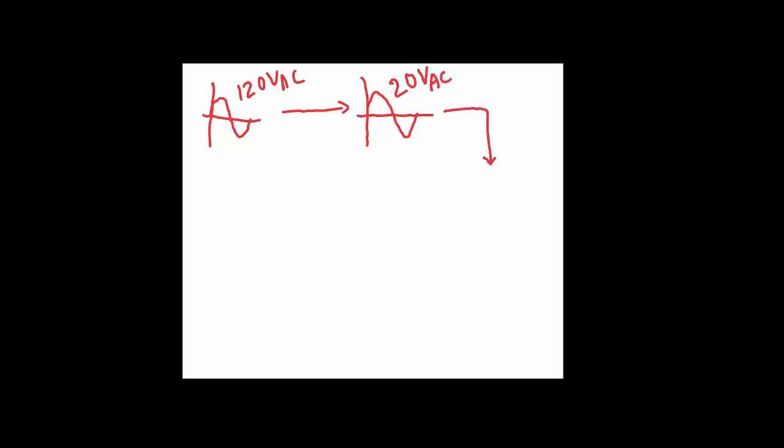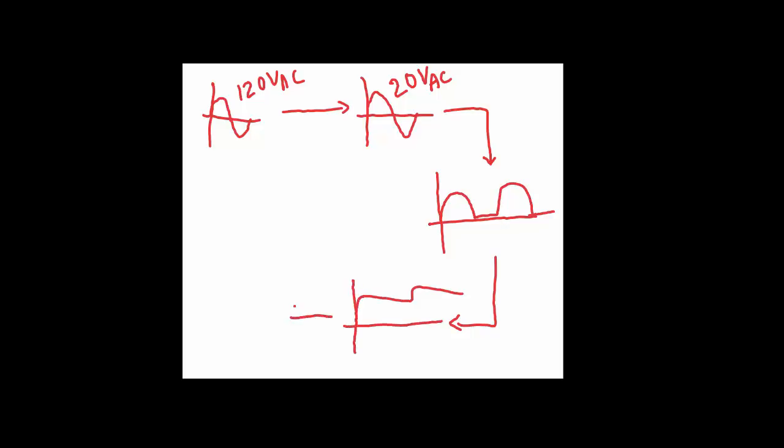So that's what a DC power supply consists of, which is going to be a wall outlet, a 120 volts AC signal, which is passed through a transformer, which is going to step down the signal. Let's say, for example, in this case, I'm going to consider it as 20 volts AC. And then this signal is going to pass through a rectifier, which is going to remove one half of the AC signal. This rectified signal will pass through a filter stage, and once the signal passes through the filter stage, that signal is going to pass through the voltage regulator.